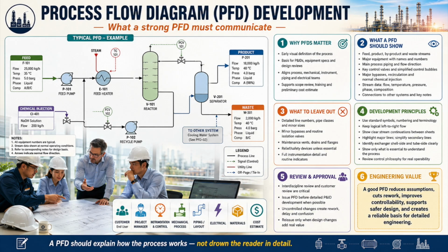The heat and material balance must be treated as an integrated part of the PFD, not as a disconnected calculation file. Show data for every numbered stream. Verify that the properties and units satisfy customer requirements. Use consistent pressure references, temperature units, flow bases, and composition conventions. Clearly distinguish operating pressure from design pressure. Clarify whether gas flow is actual or standard. Clarify whether liquid flow is mass-based or volume-based. Avoid mixing gauge and absolute pressure.